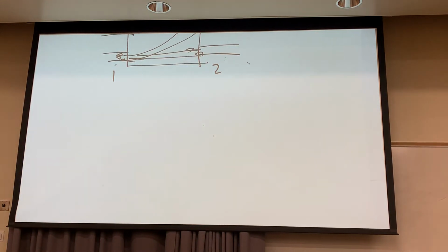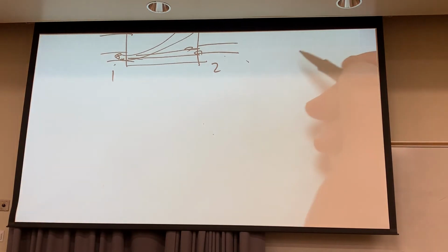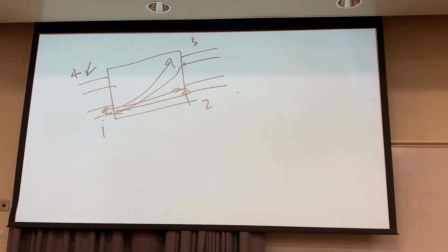Now this is called the isolation port, port 4. And the isolation port usually is not useful for anything. It's almost like this is a 3-port device, only instead of being a circulator, it's a coupler, because most of the signal goes from port 1 to port 2, but some of it's shunted off, so you get maybe 30 dB to 60 dB of attenuation.